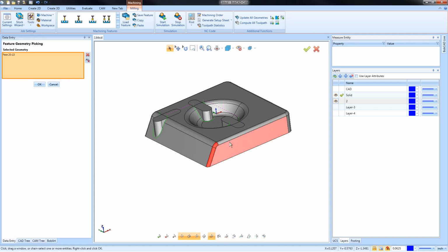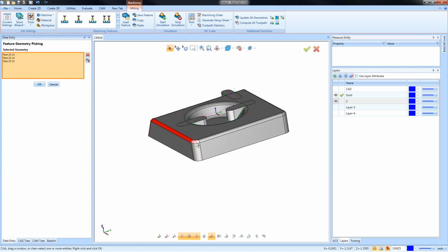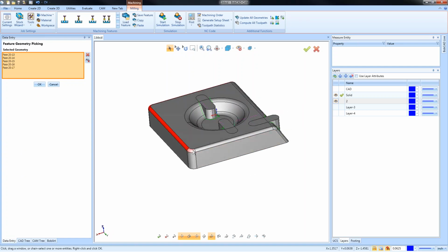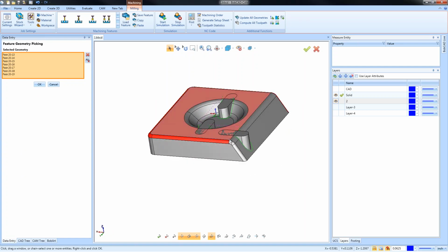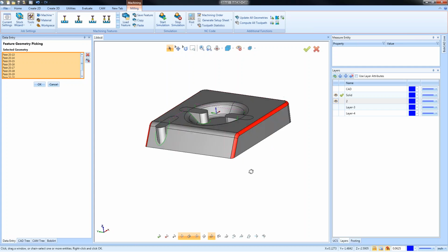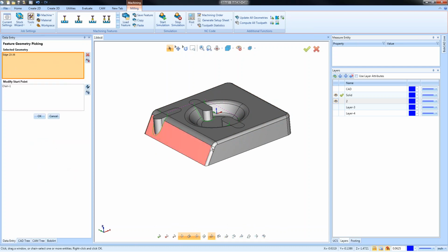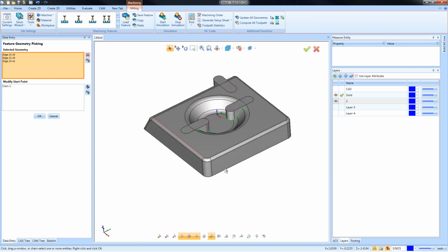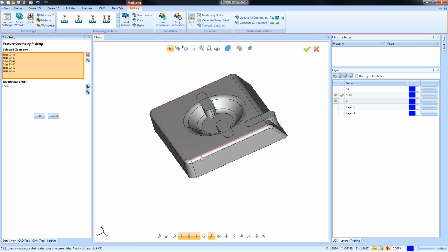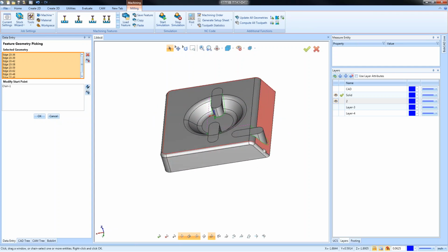And a good example here would be this radius here. If we want to target just this radius across the top of the model, again, there's a couple of different ways that we can approach it. This one I'm going to use one of the Mill Premium toolpaths. This is called project curve, this morph between two curves, and it allows you to select your drive surface that you want the toolpath to be driven along, and then you can select two curves that you want the morph to go between. So let's select that one. We'll come in and we're going to select this bottom one here.